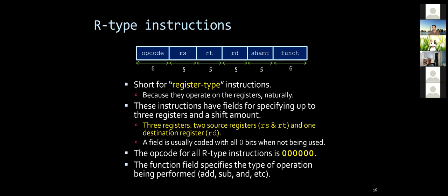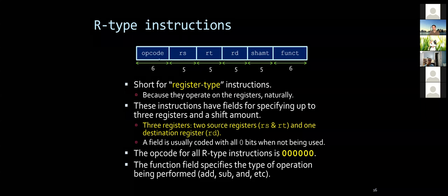So if you see the opcode zeros, you already built the circuit. You know that detecting all zeros is very fast. So I can quickly detect all zeros and I don't need to do fancy decoding. I already know I need to read this. So I can very quickly detect all zeros, right? And I know how to read the functionality. So there are multiple reasons.